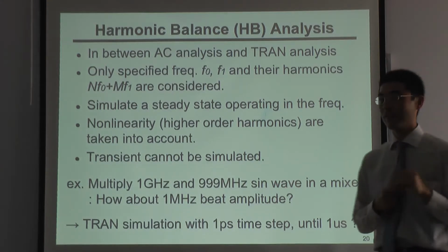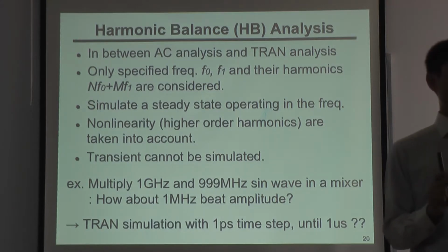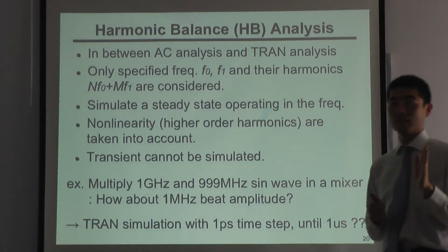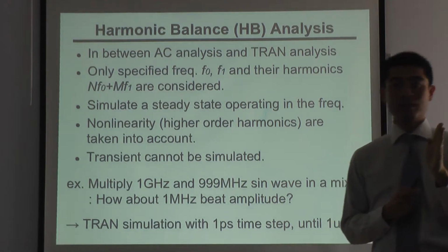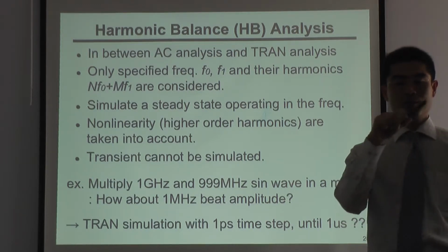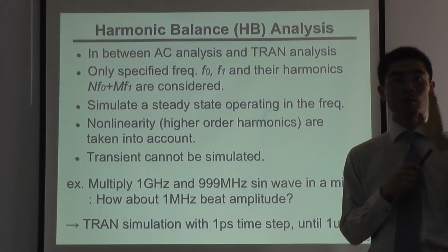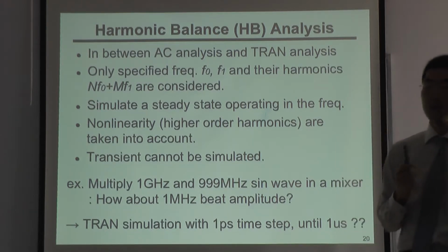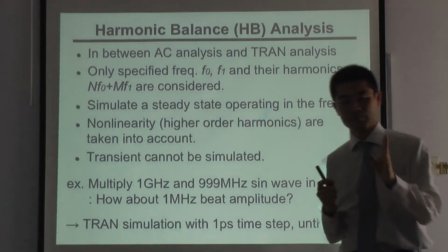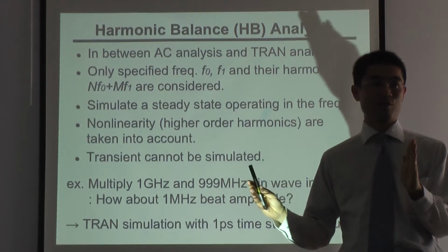Harmonic balance is a kind of simulation between AC analysis and transient analysis. For AC analysis, we specify one frequency, linearize around the bias voltage, and calculate the response at one specified frequency. And in harmonic balance analysis, we specify the frequency and how many harmonics we consider.